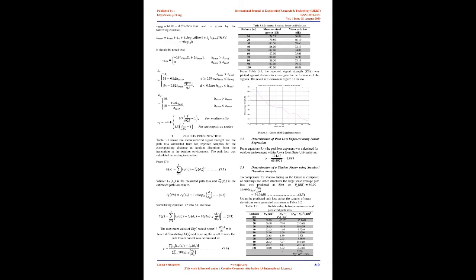2.2.1 Free Space Path Loss Model. The free space path loss considers the reduction in signal strength even when propagated in a vacuum without obstacles. This sounds ideal, and the loss is attributed to the spreading of the signal, the effective aperture of the receiver antenna, and the transmit power.